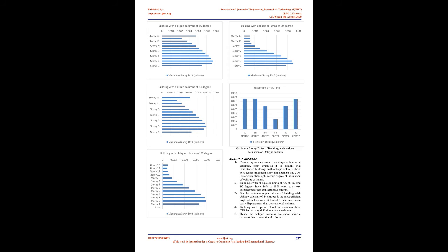Usually the response of an SDOF system is determined by time domain or frequency domain analysis, and for a given time period of the system, the maximum response is picked. This process is continued for the whole range of possible time periods of the SDOF system. The final plot with system time period on the x-axis and response quantity on the y-axis is the required response spectra for the specified damping ratio and input ground motion. The same process is repeated with different damping ratios to get the overall response spectra.